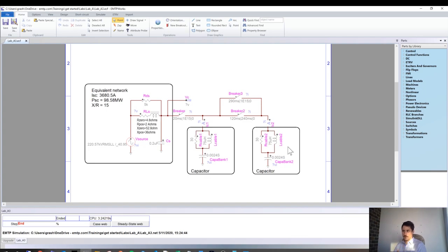basically trapped. And so if you, for example, disconnect a cap bank and re-energize it right away, you end up re-energizing a pre-energized cap bank. And you may be unlucky: for example, if you trap 1 per unit here, then the voltage here will keep oscillating at 60 hertz and go to minus 1 per unit, and by bad luck you re-energize at this time.